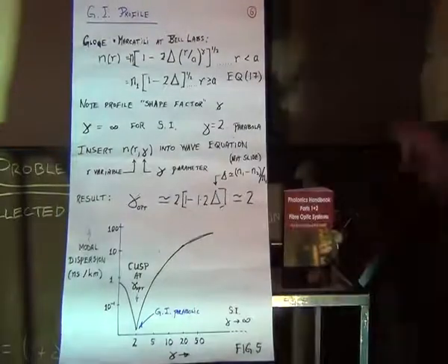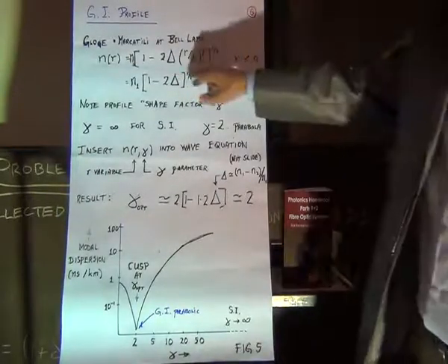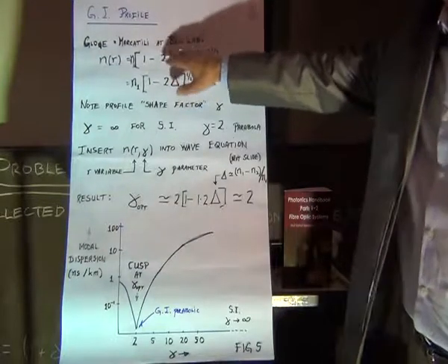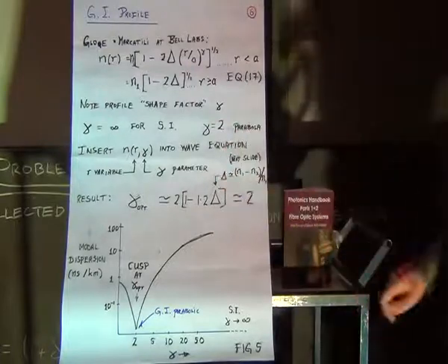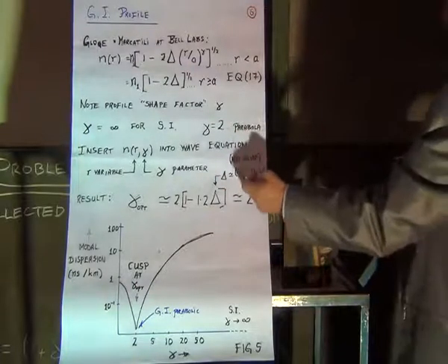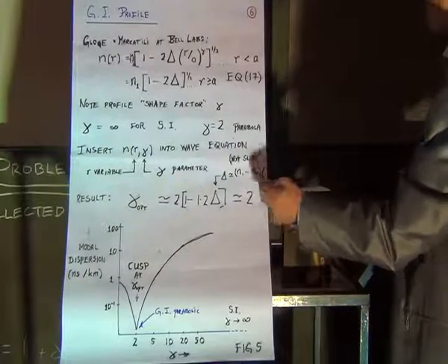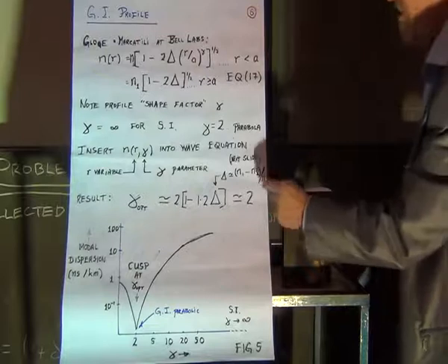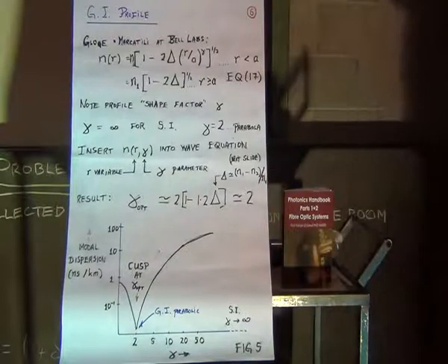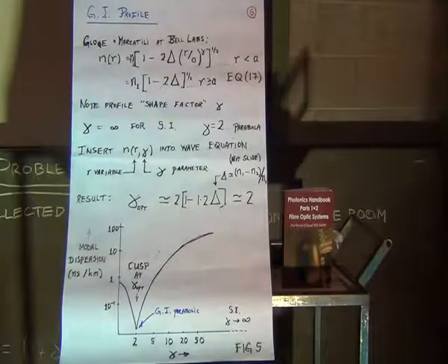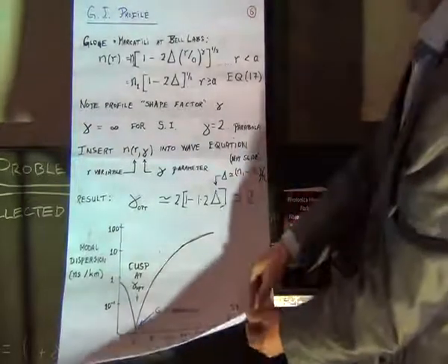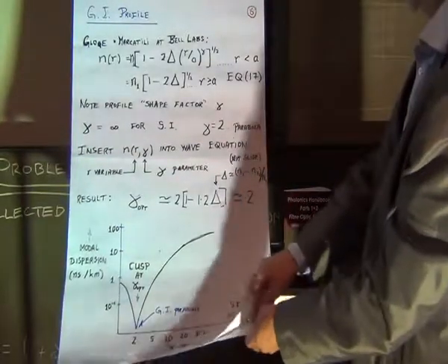relationship. Also we'll keep in mind that in the Gloge and Marcatili formula they jumbled n1, n2 altogether into this delta factor. I've written it there. The value of delta by their formula was n1 minus n2 over n1. So that would be 1.5 minus 1.49 over 1.5. That's less than 0.01. It's a fraction. It's less than 1%. So delta is a tiny number. It's a measure of the relative difference of the index between the core and the cladding.